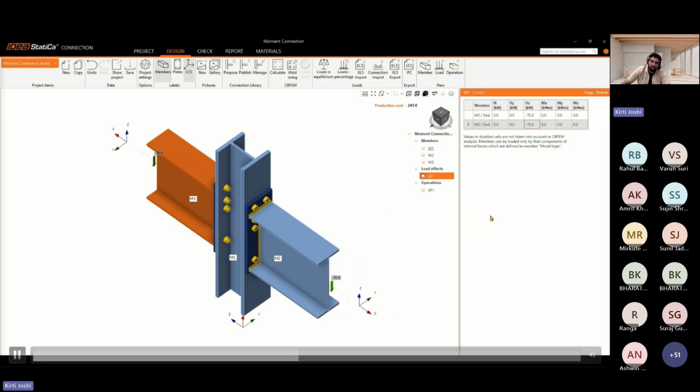I am applying shear load and moment on both ends of the beam. We'll carry out the stress-strain analysis, and at a later stage, we'll check the design joint resistance and what the additional moment capacity is that my model will carry, and we'll evaluate it.